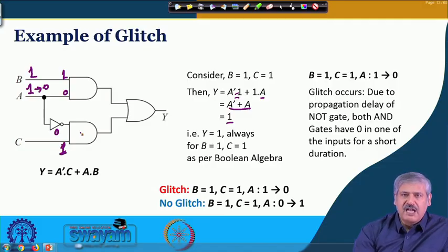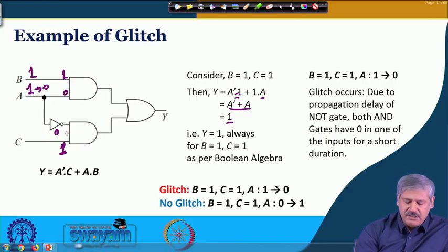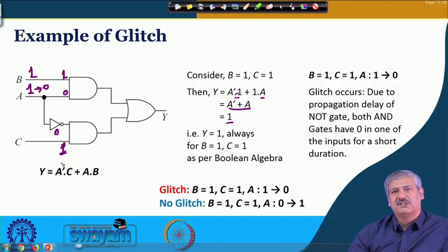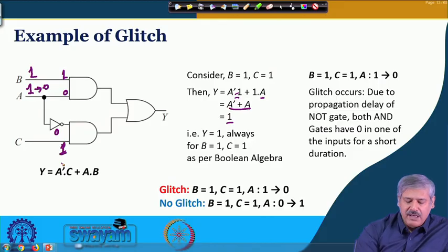So for that period, for which the NOT gate output goes from logic low to high, that is, for the propagation delay low to high, it remains at 0. So this AND gate output is 0, after of course its propagation delay, and this other one is already 0.